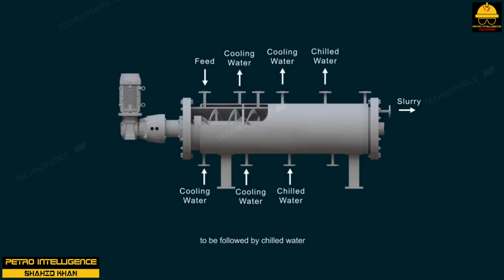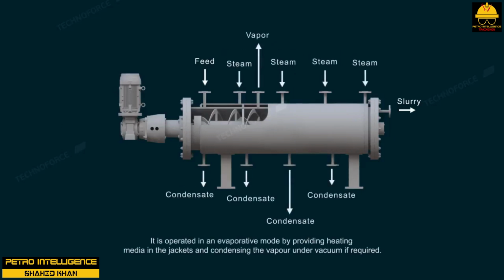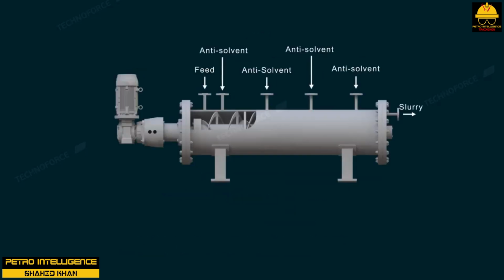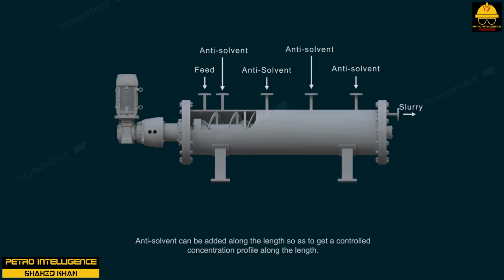The equipment used in the crystallization process can range from a simple tank to a combination of pumps, agitators, condensers, and tanks. The primary purpose of this equipment is to control the operating conditions during the crystallization process. In crystallization, the separation is possible because of differences in the size and type of molecules and differences in freezing points, melting points, and solubility. In many cases, crystallizers or centrifuges or both are used.